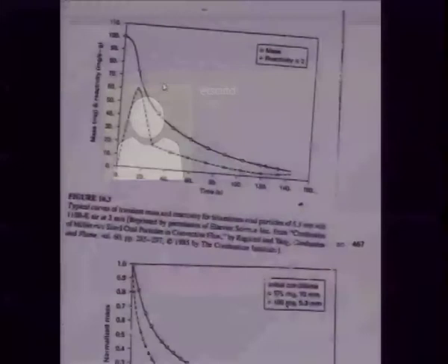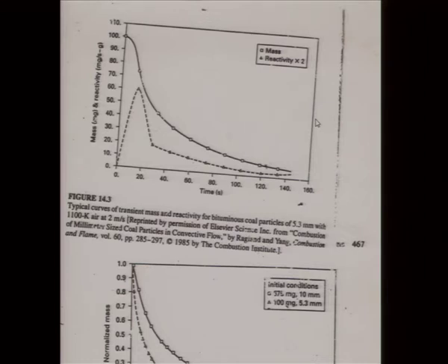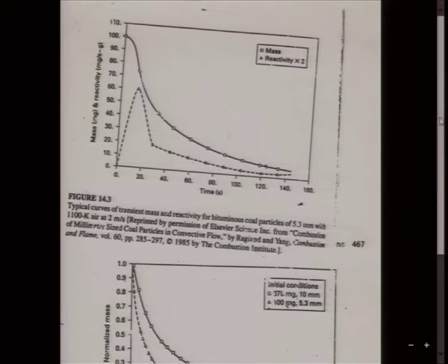And coming back to this plot, this is what I was saying, that this loses about 55% of the mass because of pyrolysis. So what do we learn from here? We learned that the approximate analysis is only indicative. It doesn't tell you exactly what will happen. Volatile matter loss can be much more.